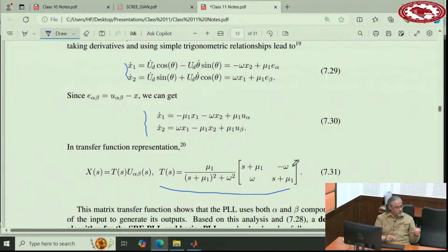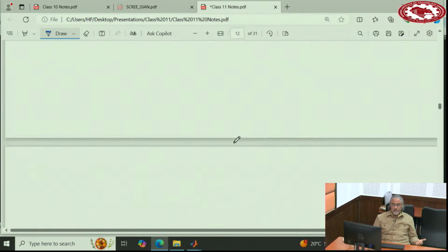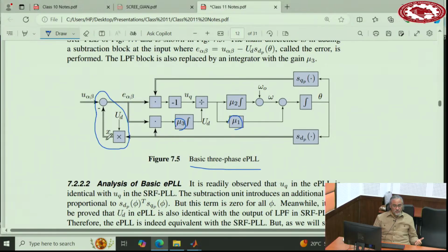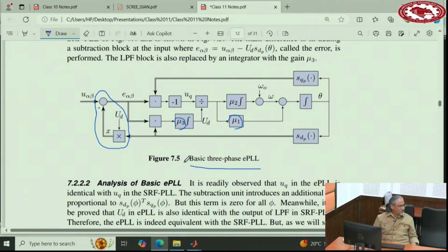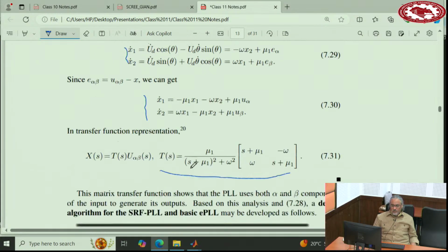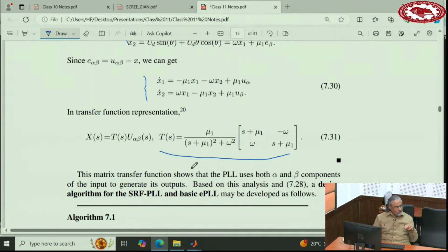They find an equilibrium point, operating point, small signal analysis. But we did not do that. We just manipulated the equations, added things, put some conditions on the parameters, and then we said in large signal, this system is linear. Not in small signal. In large signal, this system is linear with these transfer functions. We only put two conditions, mu1 equal mu3 and mu2 equal 0, which means you are operating in a tight frequency regulated situation.